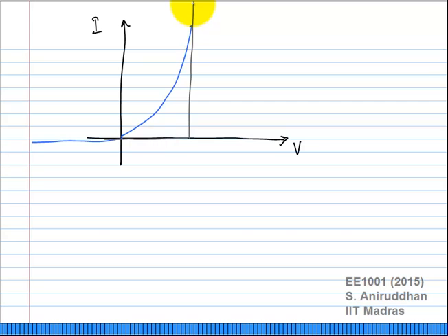This of course will only give you a crude solution, but in a majority of cases it will get you very close to the answer. I'm replacing the exponential relationship with a kind of straight line beyond a certain point. If the diode is off, when the voltage applied is less than 0.7 volts, the current is 0. But for any other current, the voltage will be 0.7 volts.